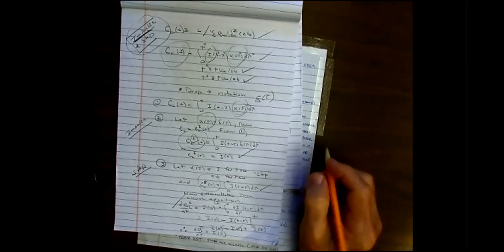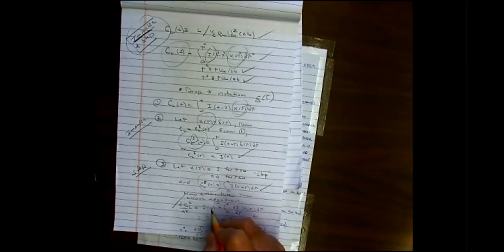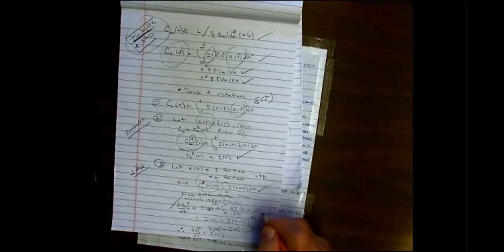If I differentiate this equation with respect to time, I get this result. The derivative of the lift coefficient due to the step with respect to time is equal to this impulse function, which I hope to find at time t equals 0, minus the integral from 0 to t of the derivative of I with respect to tau, not t, but tau, d tau.